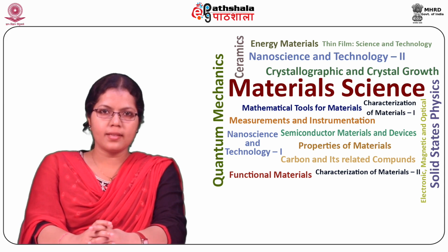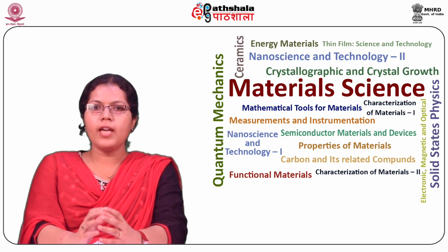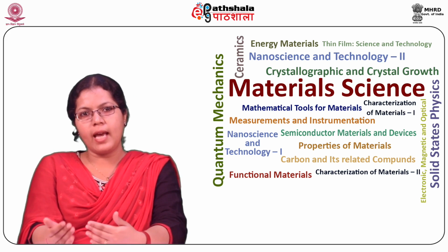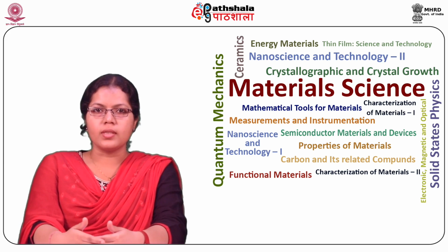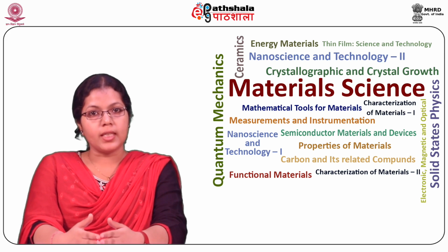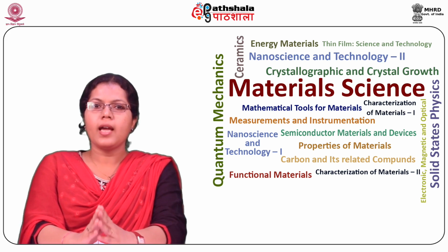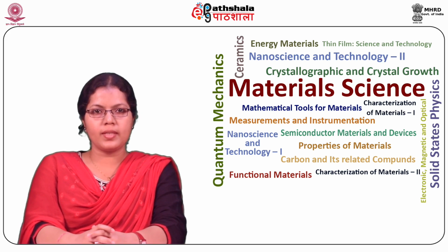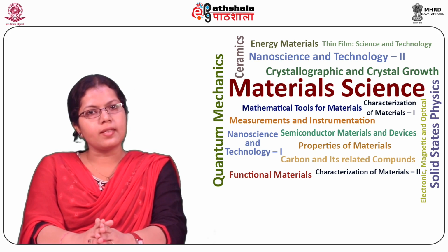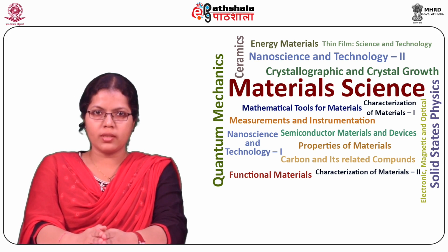So students, let us summarize what we have learned in this module. In this module, we have introduced the transducers, which are basically devices that receive energy in one form and transfer it into another convenient form or state. We studied the classification of transducers as active or passive, and also classification on the basis of being analog or digital. We discussed the electrical and magnetic phenomena used in transducers.